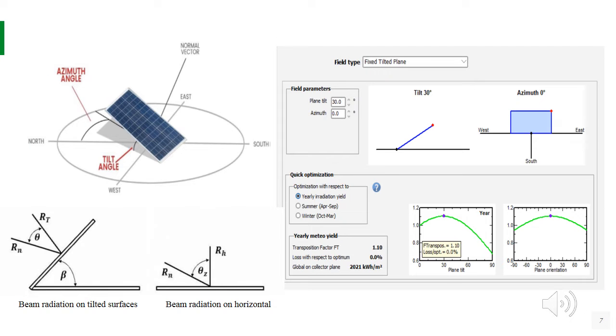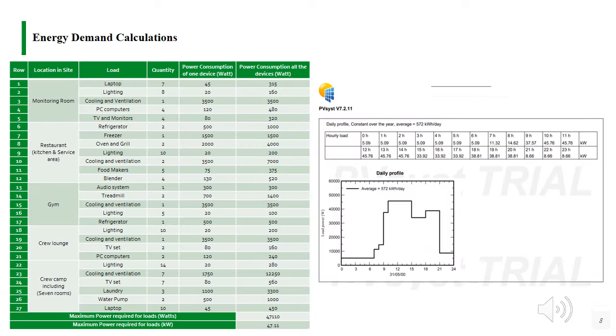Solar energy applications are typically positioned at an angle rather than horizontally to enhance the quality of radiation intercepted and reduce reflection and cosine losses. These data must be converted to radiation on a slanted surface. Here we can see the ratio of beam radiation on the slanted surface to that on a horizontal surface.